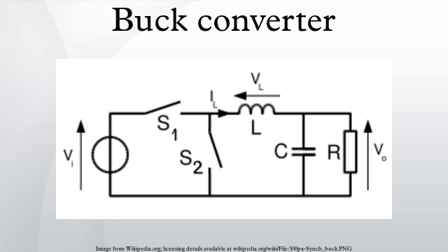Output voltage ripple. Output voltage ripple is the name given to the phenomenon where the output voltage rises during the on state and falls during the off state. Several factors contribute to this including, but not limited to, switching frequency, output capacitance, inductor, load and any current limiting features of the control circuitry. At the most basic level the output voltage will rise and fall as a result of the output capacitor charging and discharging. During the off state, the current in this equation is the load current.